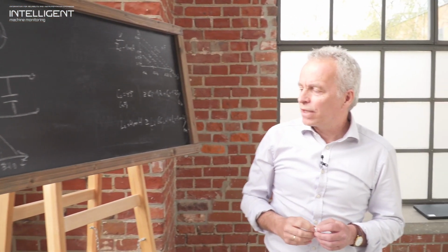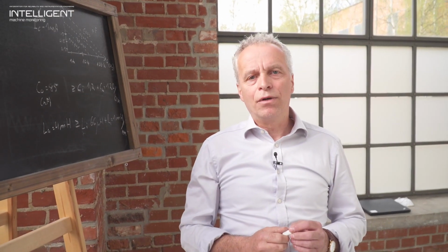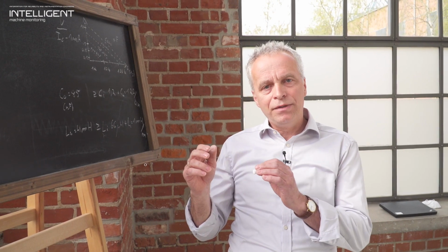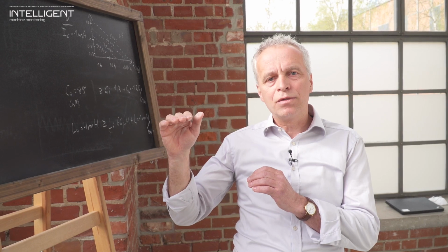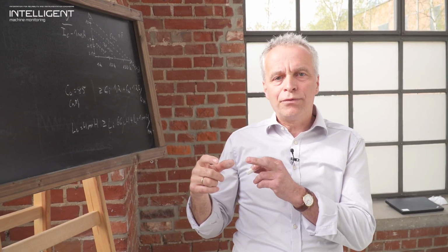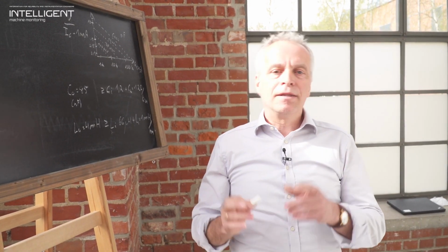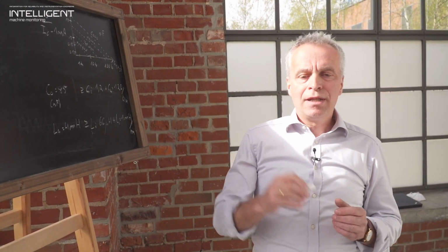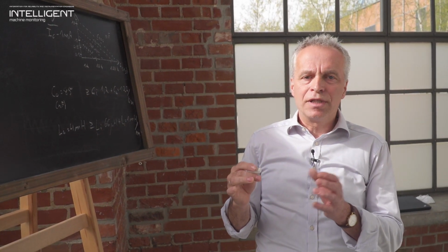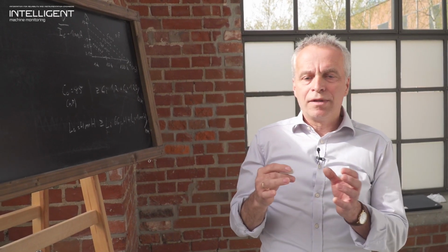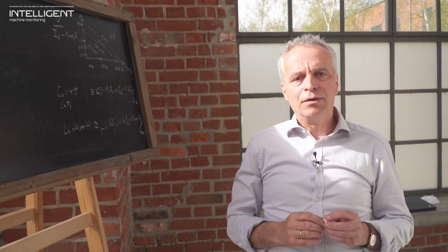From our practical experience on reciprocating compressors, we say that we need 10 kilohertz. So if we look at the valve activities at a reciprocating compressor, suction valves, discharge valves, the opening and closing, if we have, for example, a broken valve plate, you want to measure frequencies up to 10 kilohertz. The same applies for the acceleration sensors that we mount on the crosshead guide. So when you have, let's say, a loose connection between the crosshead and the piston rod, whether there is a crack or anything else, the frequencies might reach up to 10 kilohertz.